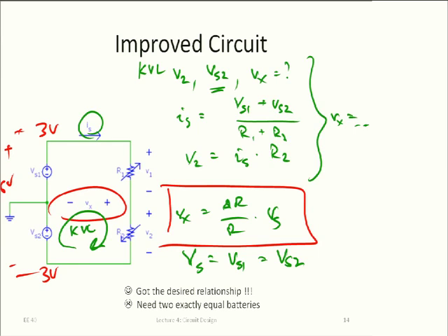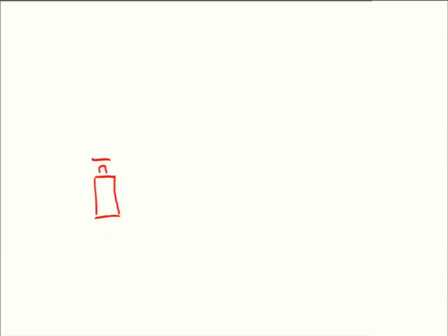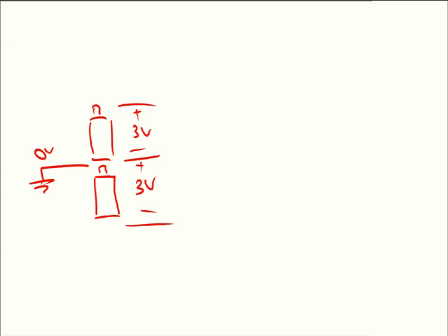So let's say I physically could take 2 batteries, right? Like this. If they're lithium batteries, then the voltage across here would be 3 volts, and across here it would be also 3 volts, right? Now I can put my ground anywhere I like, right? If I put my ground, for example, here, then I just arbitrarily say, I want to call this 0 volts. Okay? And now, of course, if I go and use my voltmeter, I find out that this voltage here, lo and behold, is 3 volts. And this voltage here is also 3 volts. Well, but now, here we have 0 volts, and then we have to subtract 3 volts, so then here I get minus 3 volts. Okay? Make sense? All right.